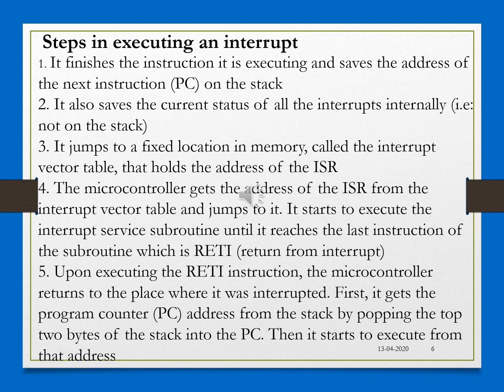We know that every subroutine ends with RET. But here, because it is the subroutine of an interrupt, the last instruction will be RETI, return from interrupt. After executing the RETI instruction, the microcontroller returns to the place where it was interrupted.